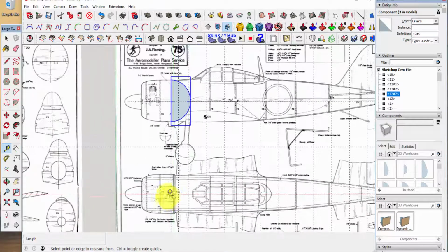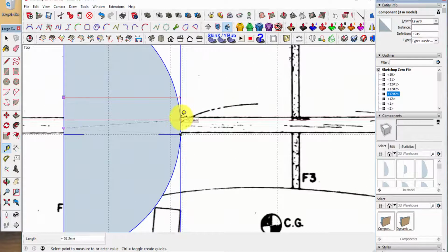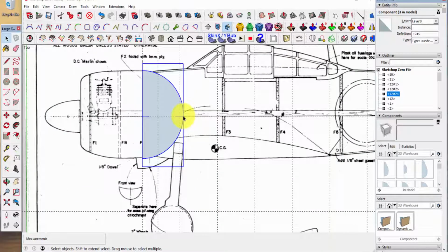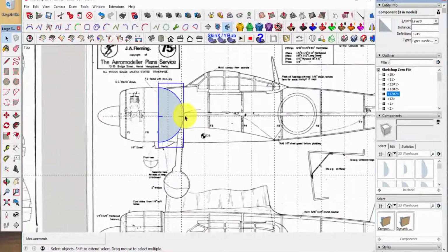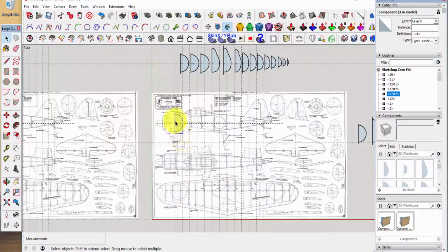So now let's go up here and see what we actually have when we drew this. Let's check it out. Tape tool again, move it this way, and is this 50? It's 52.3. That is very, very close. I'll tell you what we're going to do. We're going to just accept 52 millimeters. 2 millimeters is close enough for government work. So we do not have to resize this one. Okay, now that's just a copy, so we can delete it.